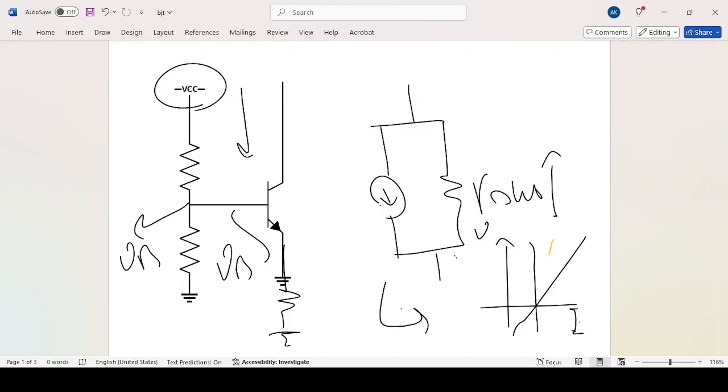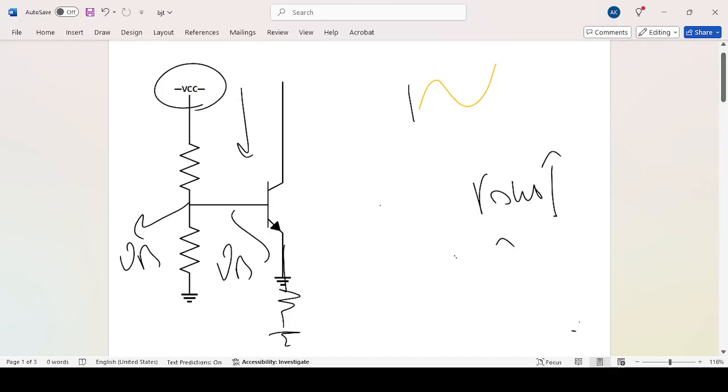Something more desirable if R out is huge, because when a signal is going through the circuit and it changes the voltage, for example, in this node, because R out, the current is changing, and when the current is changing, the specification of the circuit is changing. This is the philosophy behind it, that we always like current sources with huge R out.